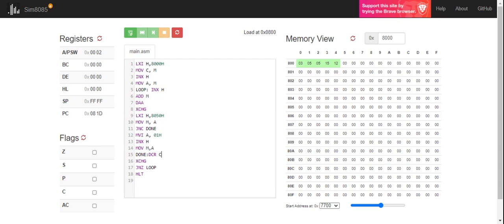So how do I get 10 from 0A? I just add 6. If I add 6 to 0A, which is the hexadecimal number, I will be getting 10. And that 10 is nothing but my decimal number 10 now. So please remember 10 is entirely different, 10 is entirely different. If I want 0A to be converted to 10, I add 6 to 0A, which becomes 10, and that 10 is now equivalent to 10. So this is what I'm going to be doing using my DAA operation.